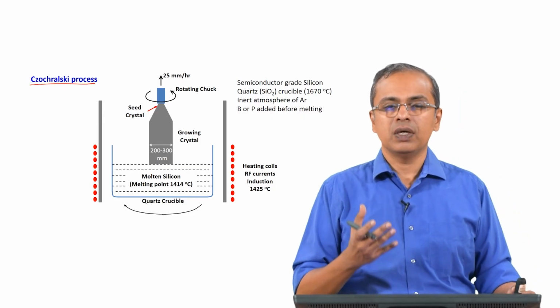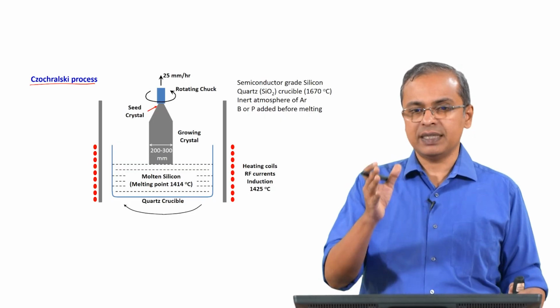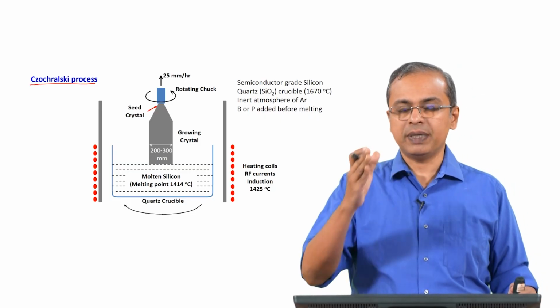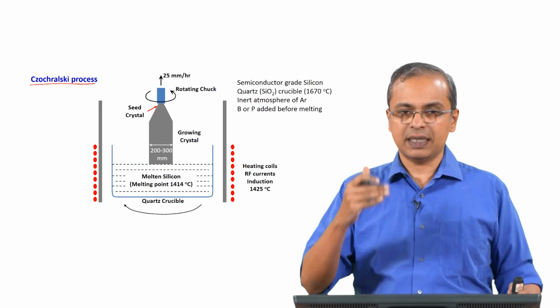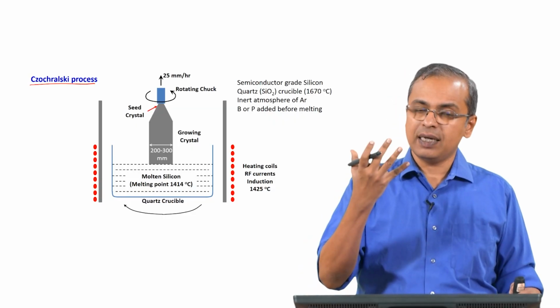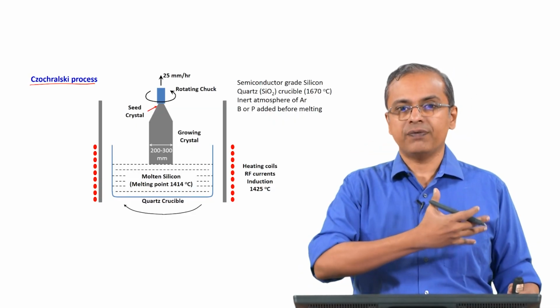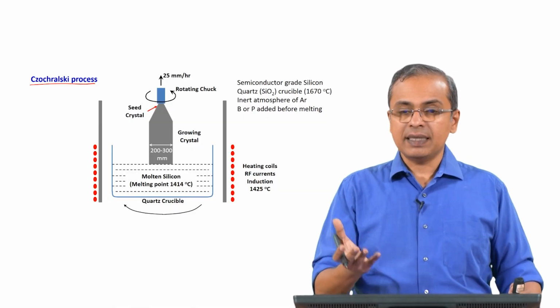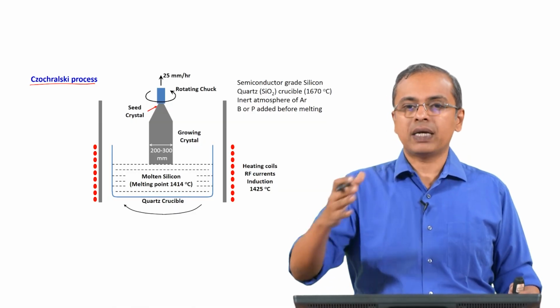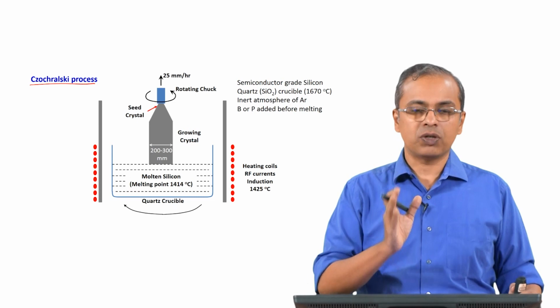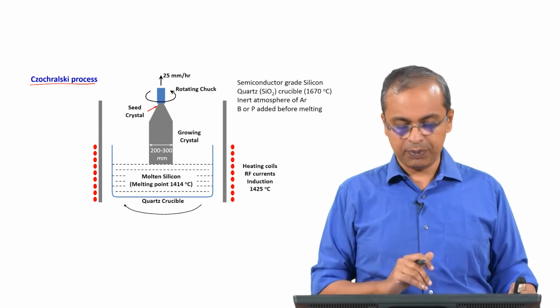Okay. So, you take something that may be polycrystalline, in which case the order is being broken repeatedly at several locations, which are those grain boundaries, and then you melt it so that you now have atoms in a molten state. When it recrystallizes you do not allow them to break order, you try to encourage them to stay ordered. So, that is the basic working principle here.